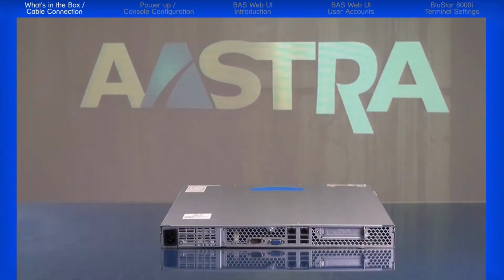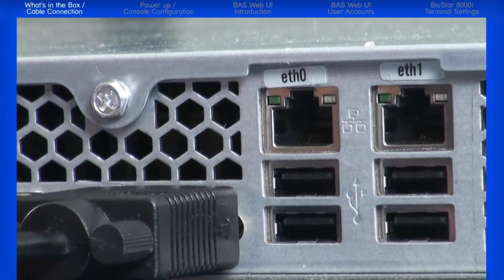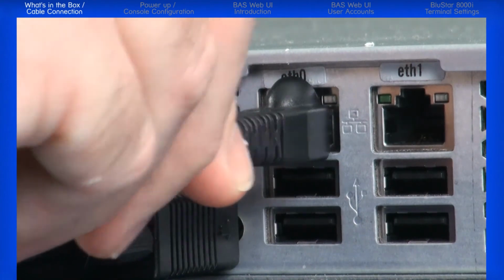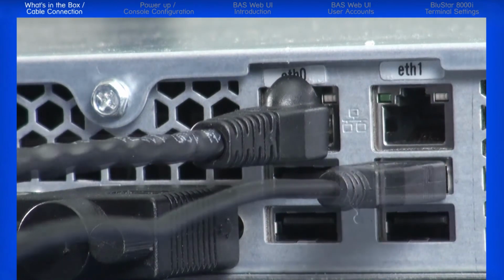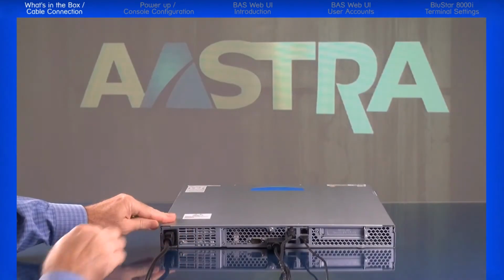Before you power up the BAS, you will need to connect a VGA monitor, an Ethernet connection. Be sure to connect the cable to Ethernet 0. It's labeled ETH0. Later, you can configure Ethernet 1 for various uses, such as to communicate with a select group of devices on a separate network. Connect a USB keyboard and the power cable.